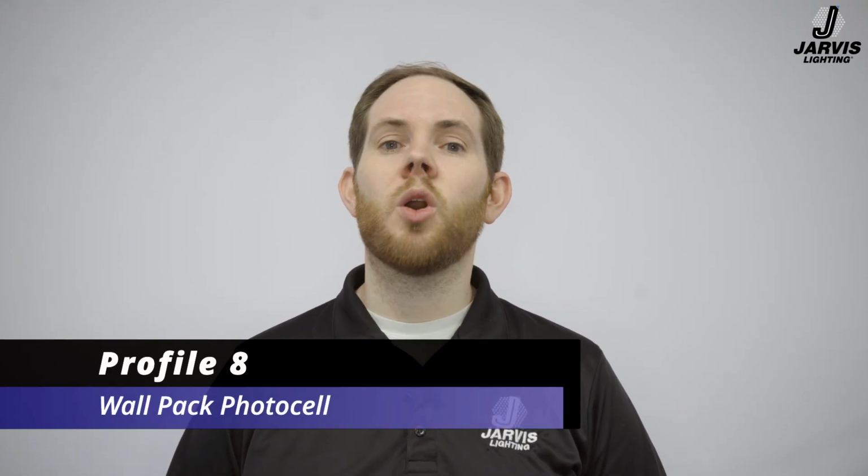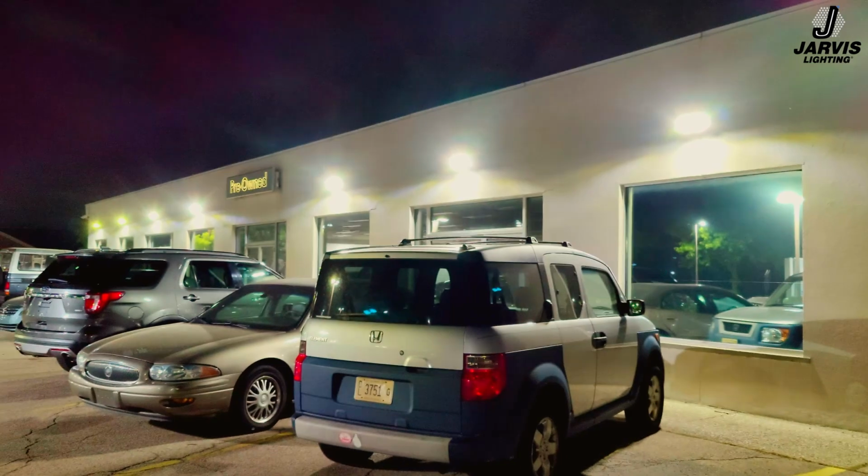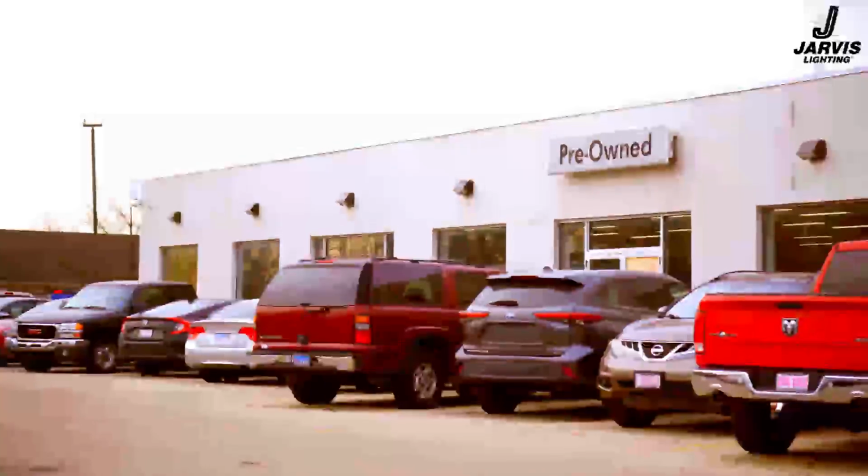Profile 8 is our wall pack photocell profile. This profile is very similar to Profile 6, the parking lot photocell profile, with the main difference being the ambient light levels at which the fixtures turn on and off. This profile is ideal for building facades that must be continuously lit at night, regardless of occupancy. Fixtures in a zone assigned this profile will turn on at dusk and off at dawn.